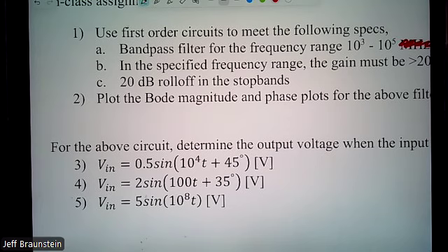So in reality, for the op-amp I use in electronics, it does have a tiny bit of current going. There are much better op-amps where the current is really small, 10 to the -12, or 10 to the -14 or something. So it is not an unreasonable expectation.